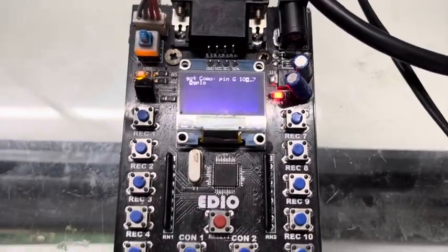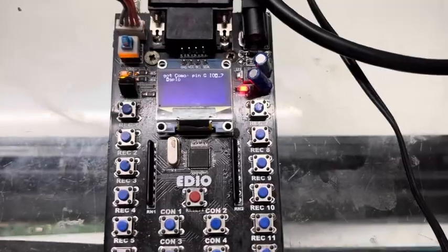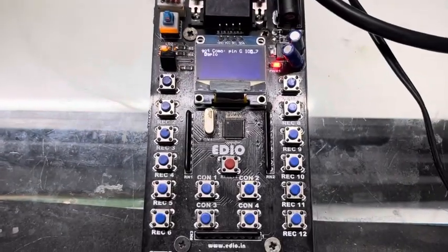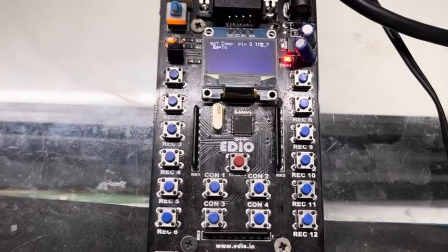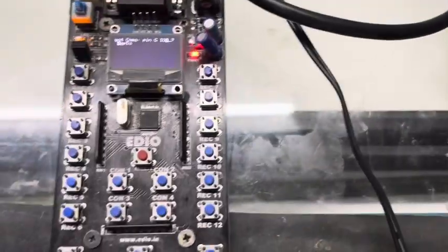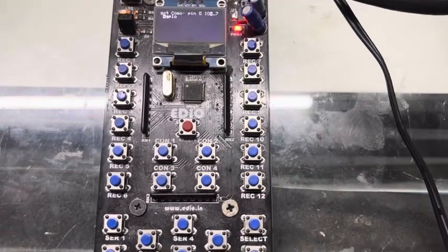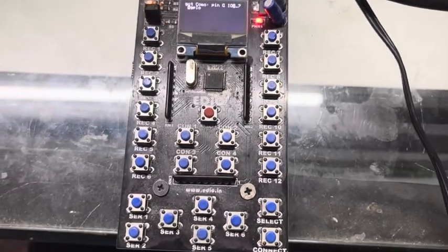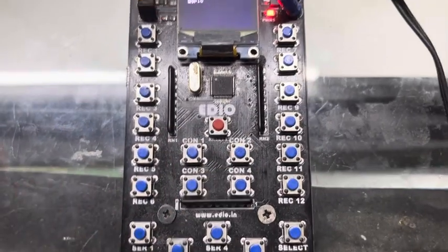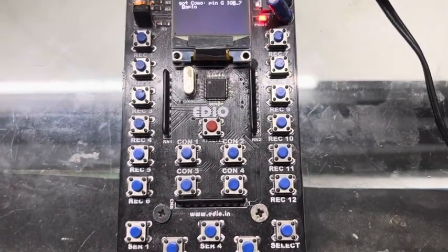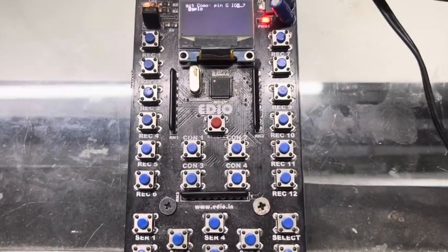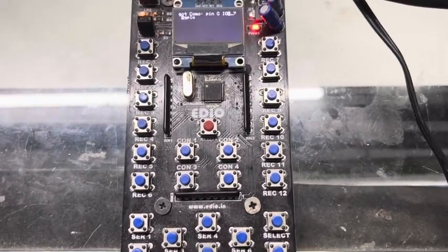Okay. So now I want to recover this motherboard. So what are you going to do? I first want to enter into the console mode. The console entering process: if you want to enter into the console mode, you have to select the console button to press based on the processor. At the same time, you have to press the console keys in power on mode or standby mode. These two things are based on the processor.